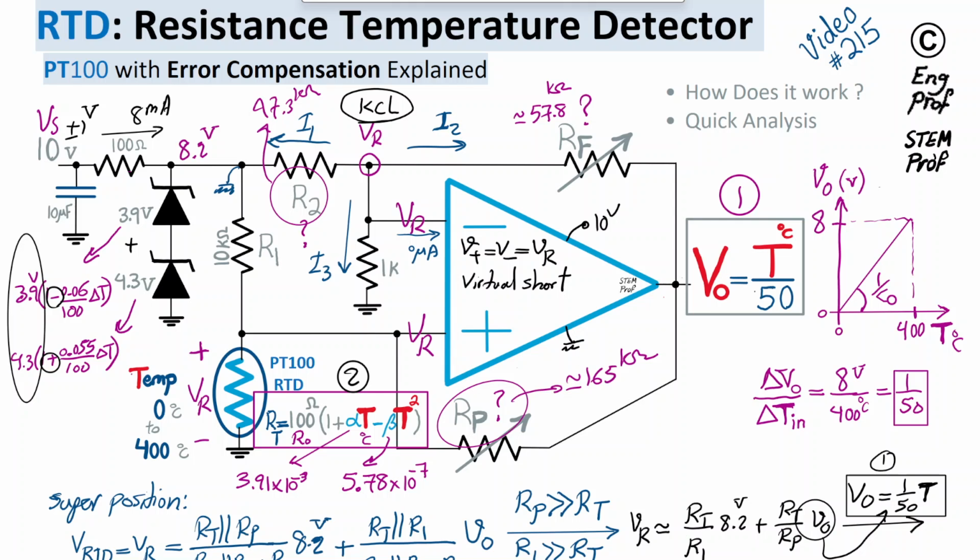So with these values found, the circuit is now designed, and it can provide this sort of a weak positive feedback that gets rid of or compensates for the error resulting from the dependency on the second order nonlinearity, and the output will now be a linear response, which was the thing we were looking for.